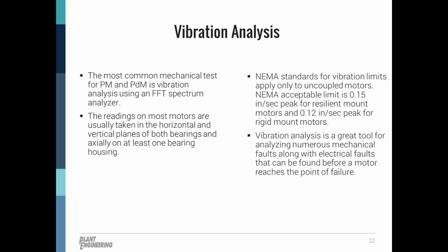So I recommend always taking vibration readings of the motor coupled to the driven equipment first, as this can also pick up any signs of misalignment, coupling wear, or even unbalance of driven equipment.